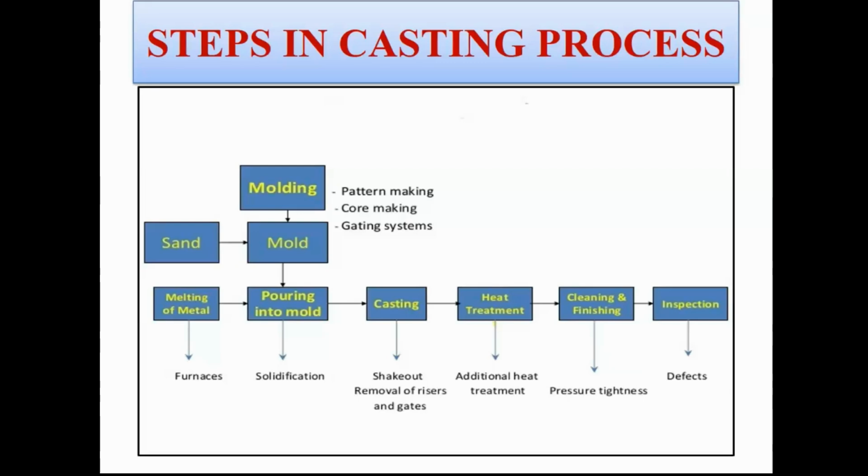which can easily remove dust, moisture, or any oil impurity from the cast surface. You should select these cleaning agents in such a way that they do not corrode your solidified product or your casting. And then in the last stage you perform the inspection. Inspection can be done with the help of visual inspection, and we have already studied various types of non-destructive testing. Those non-destructive tests can also be utilized in the inspection of the casting.